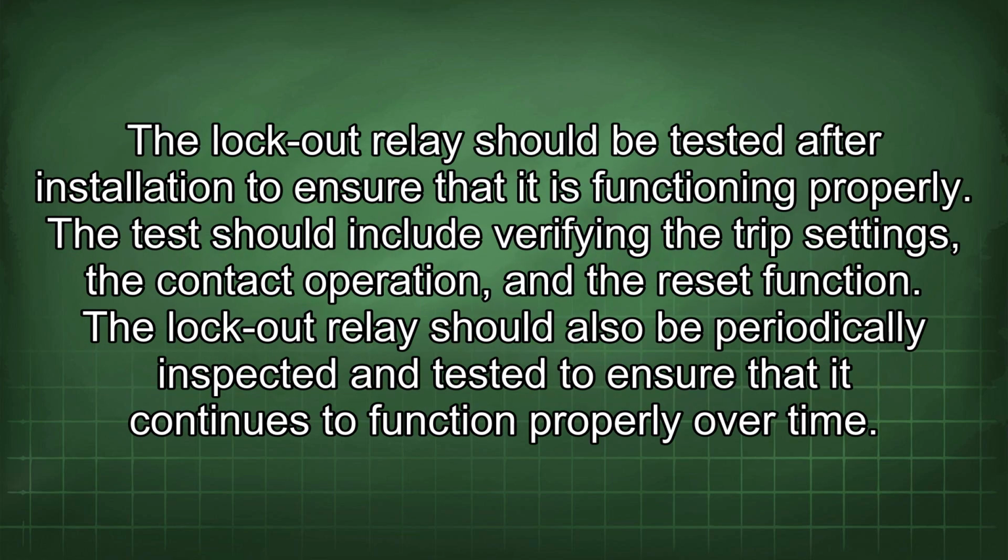The lockout relay should be tested after installation to ensure that it is functioning properly. The test should include verifying the trip settings, the contact operation, and the reset function. The lockout relay should also be periodically inspected and tested to ensure that it continues to function properly over time.